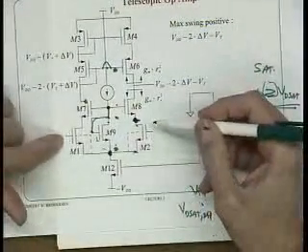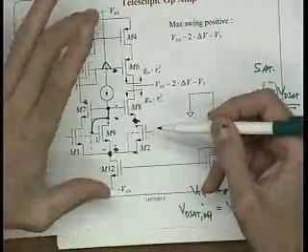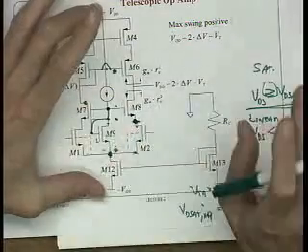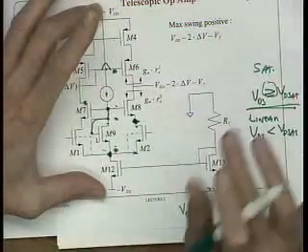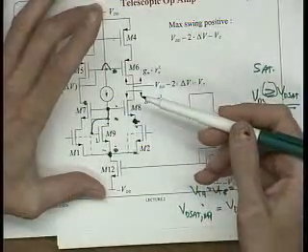What's wrong with this circuit? We mentioned it last time. The problem with this circuit is everything's stacked up. There's lots of transistors between the plus and minus supplies. In this age of small supply voltages, which are getting smaller, this is not very desirable.